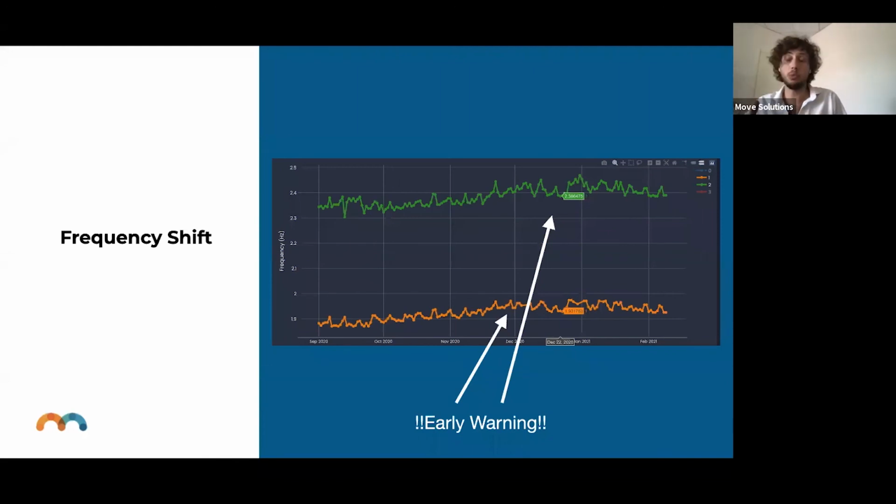So we got the early warning first, and then we were able to correlate this with the load cells that were losing force. But the frequency analysis came earlier than a significant amount of loss in the load cells. So that's really why dynamic monitoring is really good.